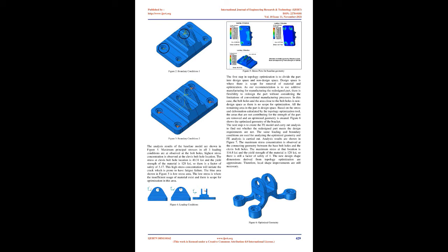B. Redesign of Aero engine bracket using structural optimization, case study. In this paper, an Aero engine bracket is considered as the subject for optimizing the weight while meeting all the design and structural requirements of the part. The component is redesigned using topology optimization, keeping the loading and boundary conditions the same. Altair solidThinking Inspire, commercial software, was used in this study. The initial geometry of the bracket is shown in Figure 1.